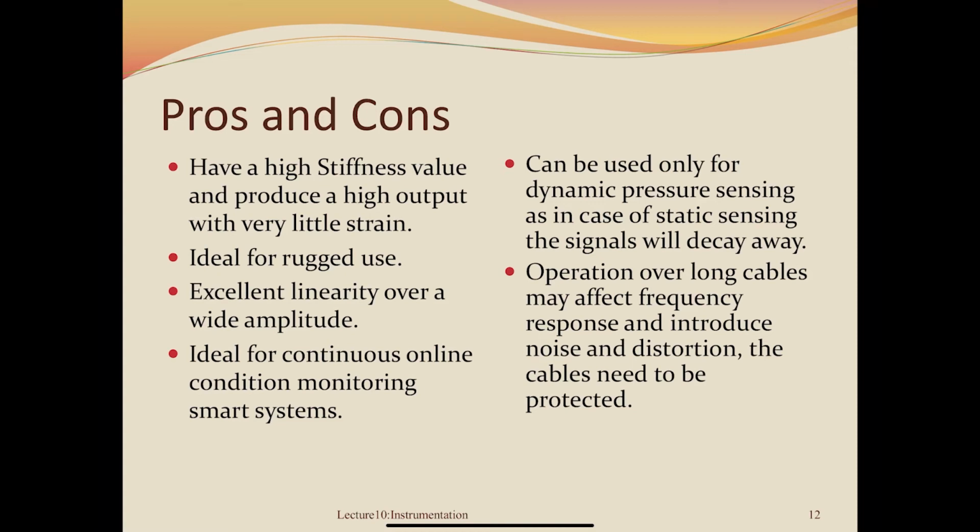And the cons of the piezoelectric sensor is that it only can be used for dynamic pressure sensing, because if the signal is static, then the signal will decay away. And the second con is the operation over long cables may affect frequency response and introduce noise and distortion. Therefore, the cables need to be protected.